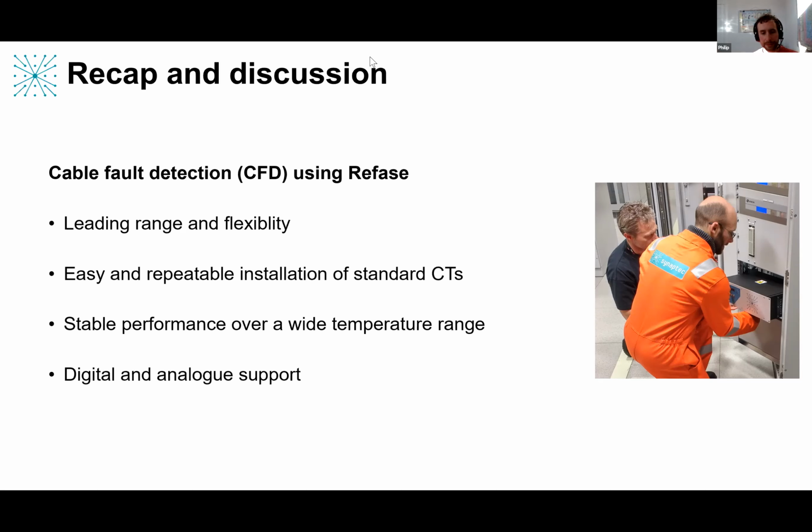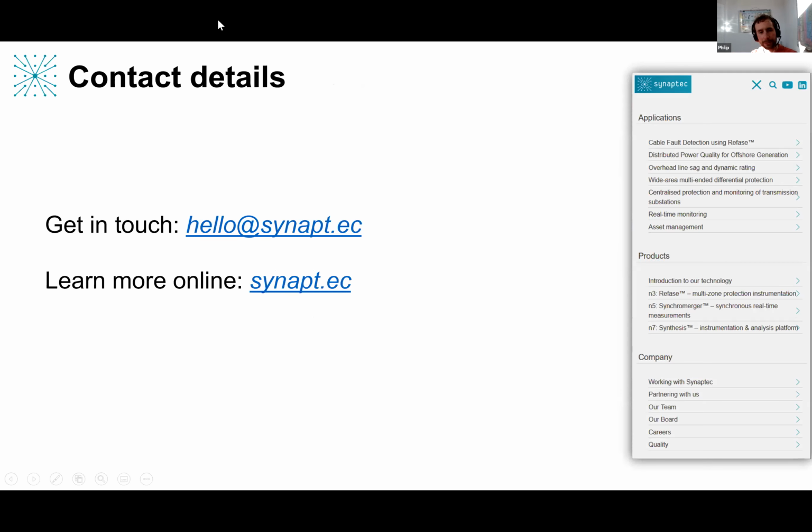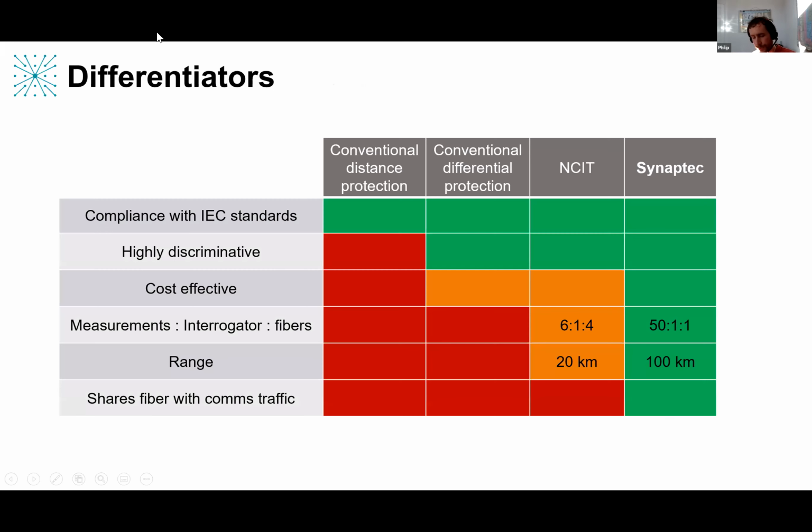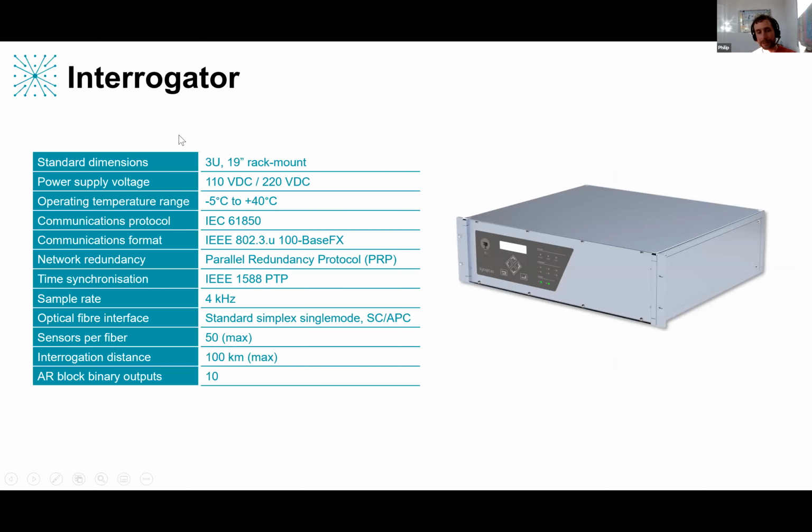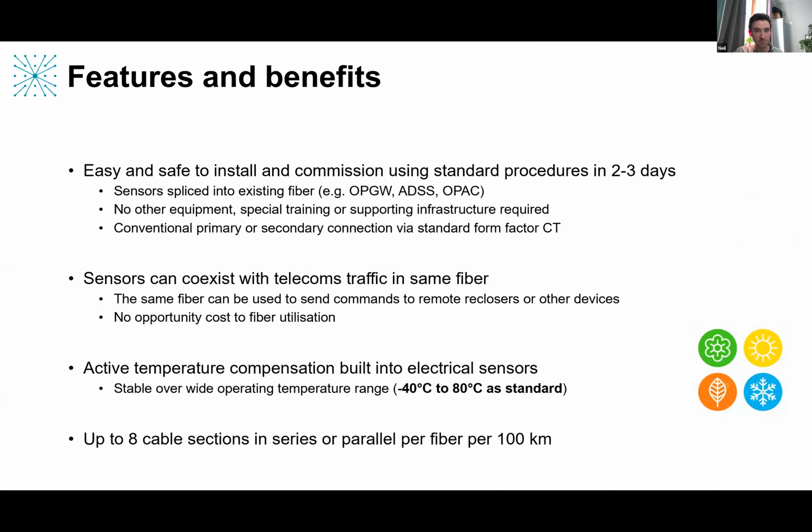Now, obviously, you have a finite speed of light in fiber, which is roughly the same as the speed of a traveling wave in a conductor, by the way, which is a good rule of thumb. So you can see it takes a microsecond every 5 kilometers or something like that, Neil. Roughly. So I wonder if it's useful, there's a slide at the end in your appendices where you talk about the time synchronization and how that's done, because it's quite interesting how that can be done with optics without needing any GPS access at the measurement locations. Yep, let me just find it. It's in here somewhere.